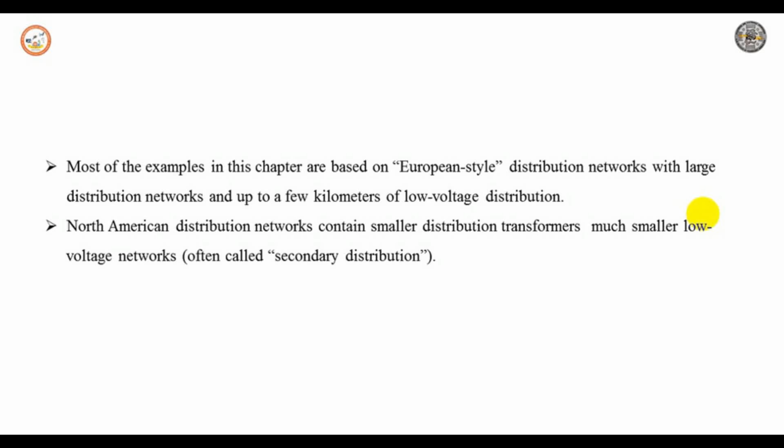According to IEC 61000, the methodology and specification of instrumentation for measuring flickering is defined. The IEEE voltage flicker working group has recently agreed to adopt these standards. They were amended for 60 Hertz, which is currently used in North America. These standards provide a simple means of describing the potential for visible light flickering through voltage measurements.